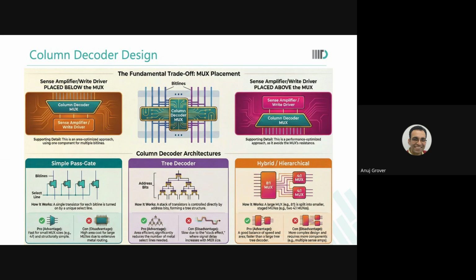That's the difference. Some 2-3 questions related to the quiz. There was one question: what is the main function of the equalization transistor during bitline recharge? The answer was just to ensure both bitlines begin each cycle at nearly identical voltages. Why could it not be to minimize the sense amplifier offset as well? Both are the same thing. Wait.